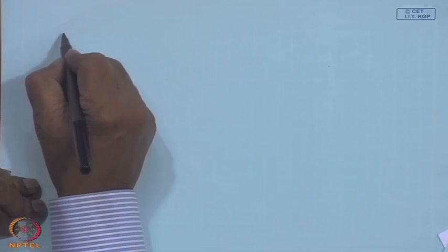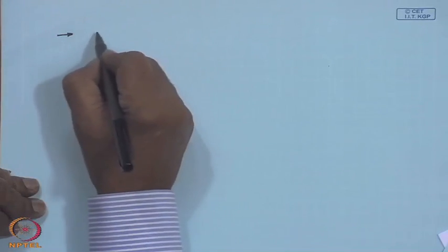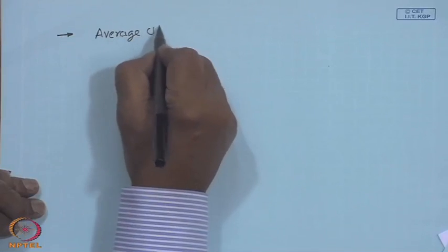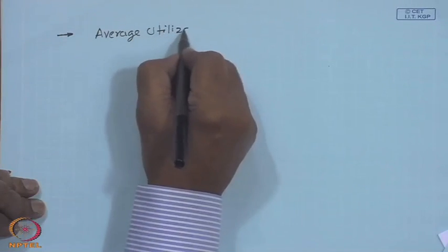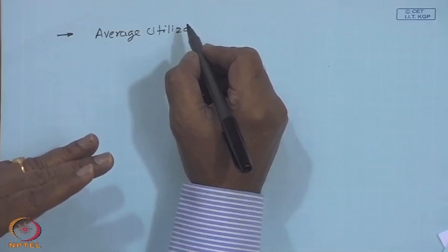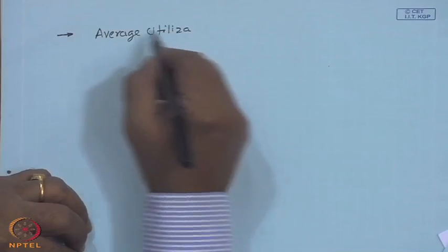So, this we said as an iterative process. To set up the iterative process, average utilizability, not the maximum, because this is an overall load fraction met by the solar energy system, which does not distinguish between the load on the system as needed by the consumer and the load because of the additional tank losses to be met by the system.